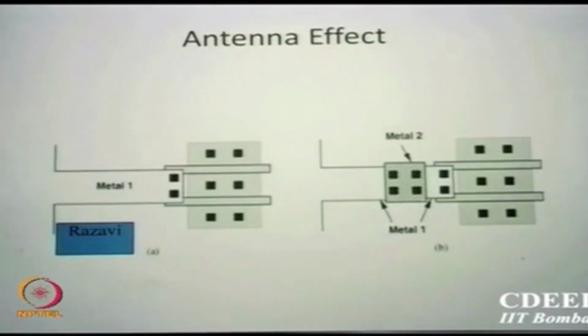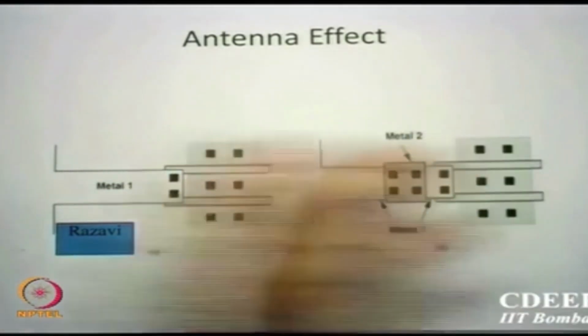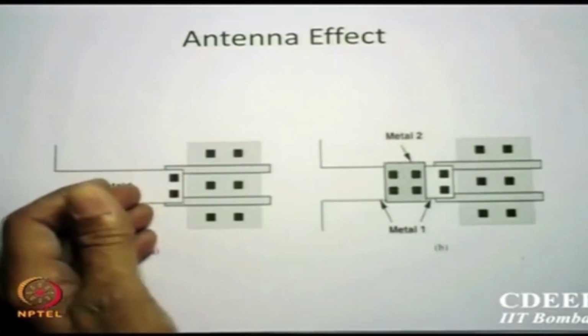In any insulator, if you run a metal line, it acts like an antenna, a radiating system. This is what we do in MICs. Instead of an alumina substrate or other substrate, you have silicon dioxide substrates. So it runs like an antenna and radiates power. If you calculate the Poynting vector here, the huge power loss is at this end.